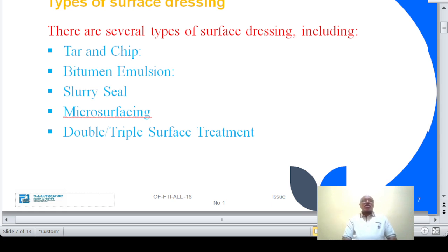Pre-coating is usually undertaken in a hot mix plant, and the hardness of the coating, and thus the tendency of the chippings to adhere to each other, can be controlled by the mixing temperature and or duration of mixing. Typically, coating temperatures are about 140 degrees centigrade for bitumen binder and 120 degrees centigrade for tar binder. Let's see bitumen for surface dressing.